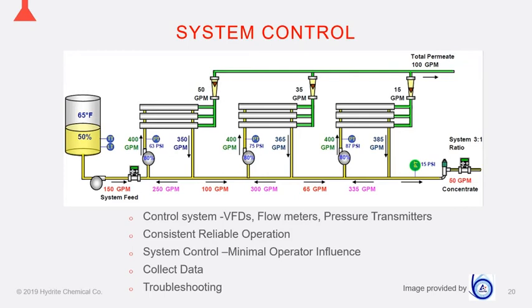So this is really kind of what you would see. The balance tanks will have a temperature transmitter and level transmitter. It's very important that we know what those levels are for CIP so we can determine hold-up volumes. There are pressure transmitters on each stage, or pressure gauges, which is valuable for us to determine that cross flow. And typically the pumps will also have an output percentage, so we can actually see what's going on with the pumps, whether they're running at the right percentage or output.